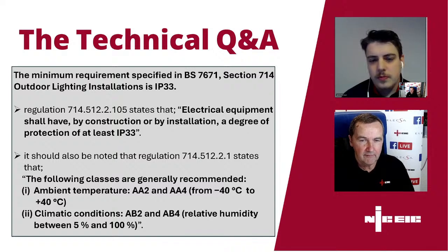So if at the first 5-year check it's noticed that it's now doubled from 0.46, then that's information that you should go back to the DNO with, because it could be an indication that you've got a problem, insulation perhaps breaking down in the distribution network. So yeah, definitely record it.